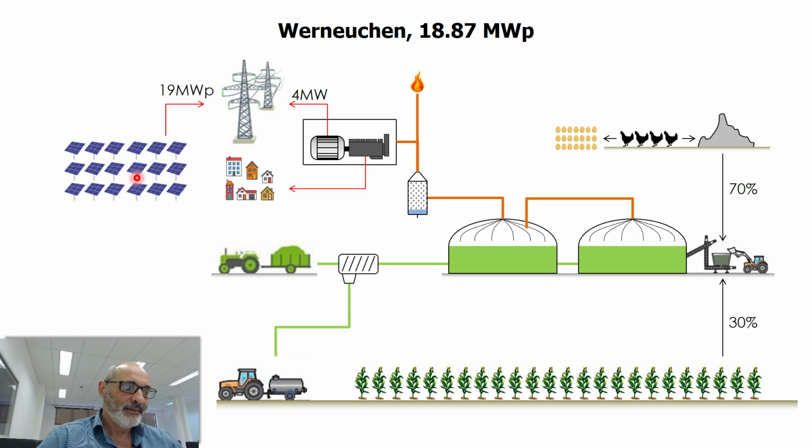Okay. Thanks. So you also have photovoltaics in that contaminated area, and the advantage of mixing photovoltaics with electricity from biogas is that the intermittency of the photovoltaic generation is compensated by the production of electricity from biogas. That's a very important aspect because biogas is a very stable means of producing electricity, and the sun is not. During the night you're not going to generate, but even during the day, you may have a very cloudy day and the generation drops to almost zero. So you have to do something in order to compensate for these intermittencies.